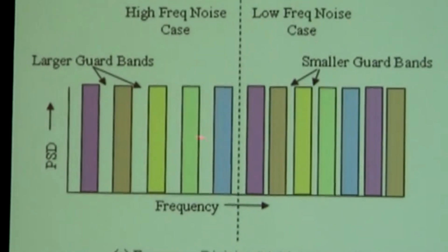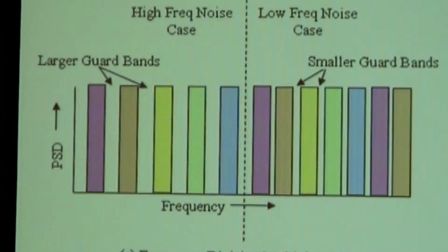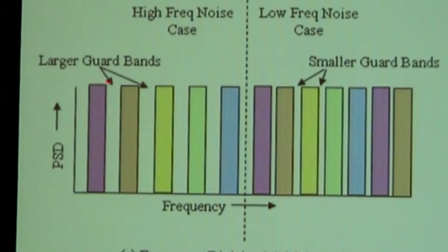Because there's some frequency uncertainty between every band of frequency space, there are these guard bands that appear between the frequency assignments. We can shrink those guard bands if we know exactly what our frequencies are. And so it's easy to see that either way, with FDMA or with frequency hop spread spectrum, you can get much more bandwidth efficiency by using a frequency standard.